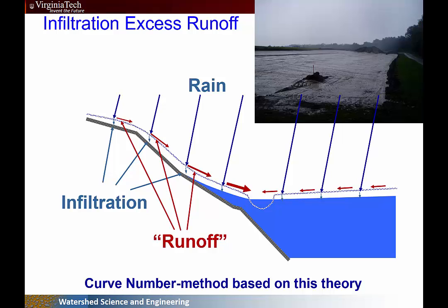And this is an image. This is a new pad getting ready to be used here. The runoff rate is relatively constant across this entire pad. It's compacted so you don't get much infiltration. You get the surface runoff leaving this area.